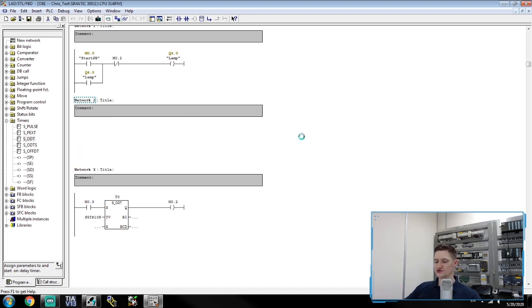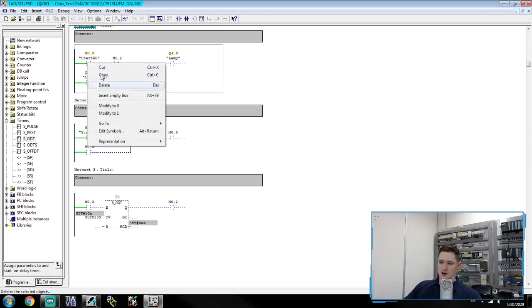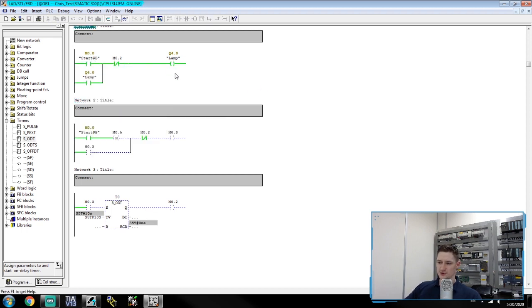So let's go to our goggles there. Let's turn on our start push button, and there you go. Our lamp is on, our timer isn't running, everything else is as it was. Like I say, let's say that was our process running signal. Our process is currently running, our extraction fan is currently on. When our process run turns off, however, that is when this flag is turned on, our timer begins to run. 3, 2, 1, it then resets our lamp. And we're ready to go once again.